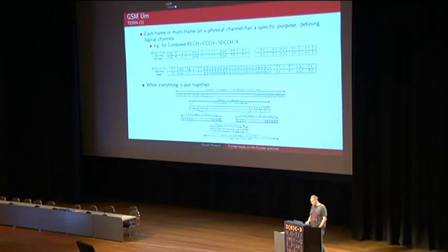So the second layer of TDMA, I would say, is what's called multiframes. On each of these physical channels, depending on the frame number, you will have a specific burst that you will find there. So let's say that this is a multiframe, okay? And so you take the frame number, you do the frame number modulo 51 in this case because the multiframe has 51 bursts. And if it's equal to, let's say, 10, well, you're going to find a FCCH burst. And this multiplex essentially creates logical channels inside the physical channels.